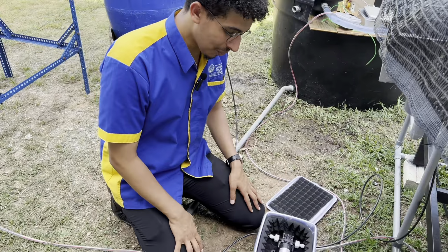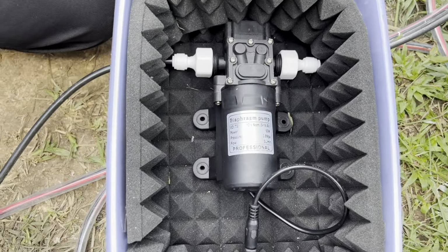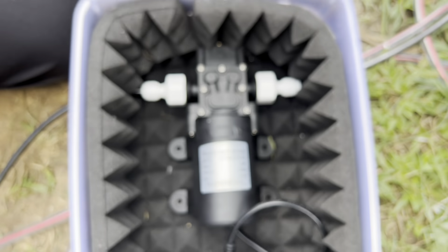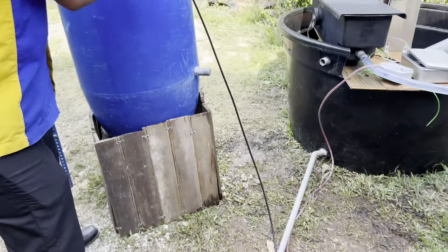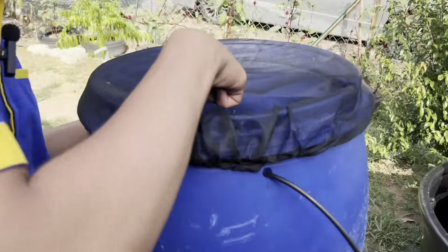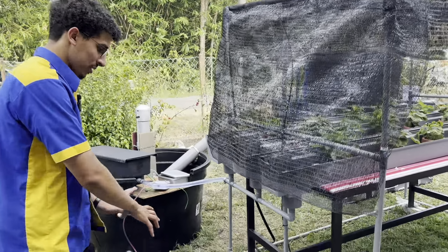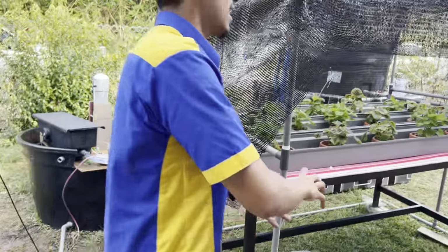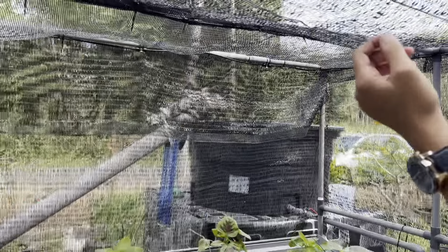Now I will explain the cooling subsystem, which is via the water irrigation mist. The main component of the water irrigation mist is our pump here, which is 0.8 megapascal and can supply a flow of 4 liters per minute. Basically, the water will be sucked directly from our rain harvesting tank through the water filter. After the water has been sucked by the pump, it will be pumped to our water mist.